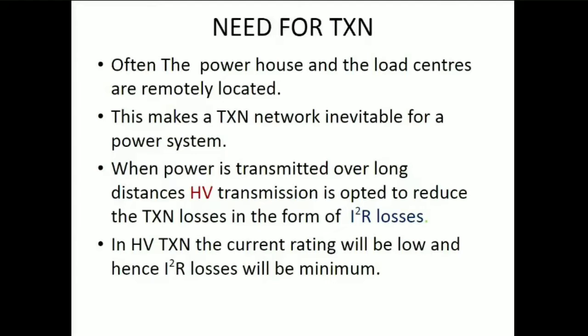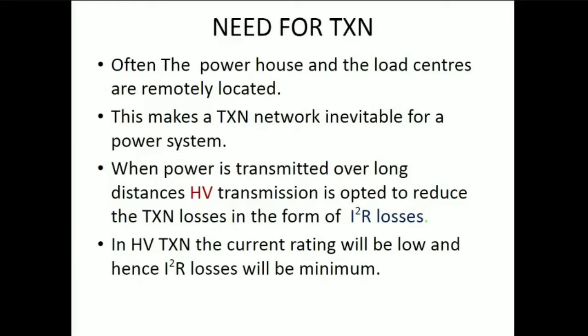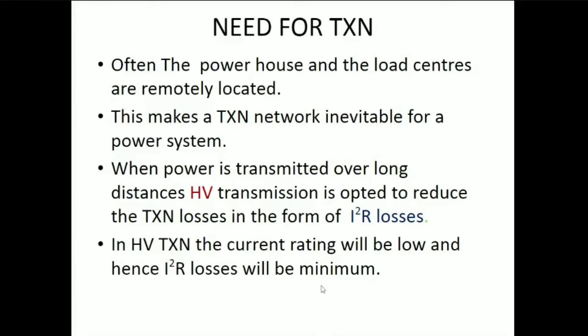What is the need for transmission? Often the powerhouse and the load centers are remotely located. This makes a transmission network inevitable for a power system. When power is transmitted over long distances, high voltage transmission is opted to reduce the transmission losses in the form of I²R losses. In high voltage transmission, the current rating will be low and hence I²R losses will be minimum.